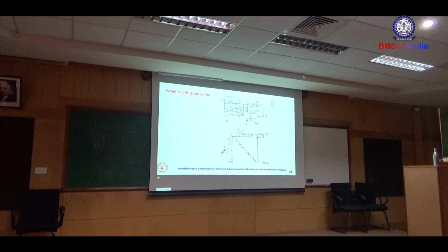What is the resolution then? For this circuit, what is the resolution? Do you know the definition of resolution? Resolution is the smallest possible voltage change with respect to the change in the input signal. When changing the level from 0 to 1, what is the shift? It's nothing but a step size. You can say resolution is nothing but step size. In your laboratory you have done the calculation. The step size is nothing but minus 0.5 volts.